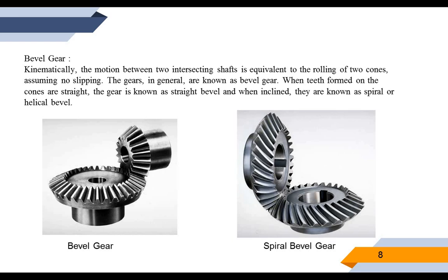In this session we covered the different types of gears. When these different types of gears engage with each other, that becomes a gear train. Generally the bevel gears are also used for the different drives of automobiles, as are spur, and rack and pinion. Helical gears are used for greater loads at higher velocities. So gears are used in different machineries.